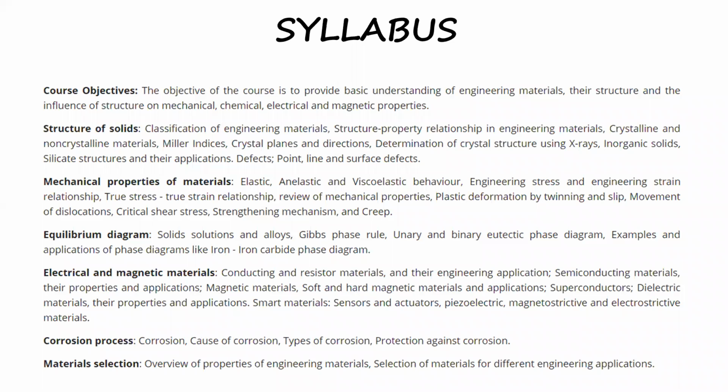So like a logarithmic table, you have an equilibrium phase diagram for every material available in the standard literature. We will learn how to read them, and once you understand how to read them, we will use them for designing and predicting the structure and property correlation of the material.